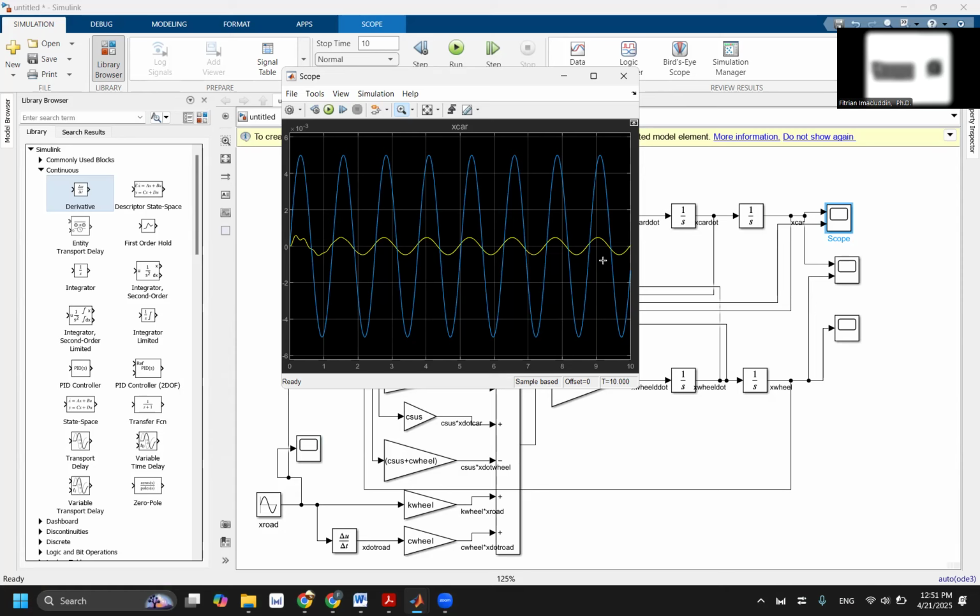So the question is probably, what suspension tuning should be done to make the person feel comfortable in the head? You know, in some cases, vibration really hits your brain. You feel pain not in the whole body, but in the head. So if you can model the K and C of the human body, and this is actually one of the special fields in engineering, human factors, you can model the whole body. You can actually model and predict the level of comfort.